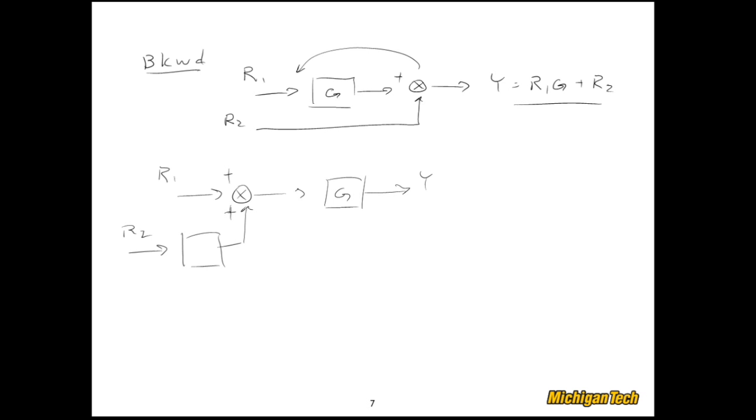And so now let's start putting together the pieces that we have. We have R1 here moving through G. So that's good, that's that part. But now if we just take R2, it would also go through G, and we don't want that, so we'll have to divide through by a G here to get plus R2 over G times G. And so the G's cancel, and we get exactly what we need. Okay, so that's it for moving summing junctions.